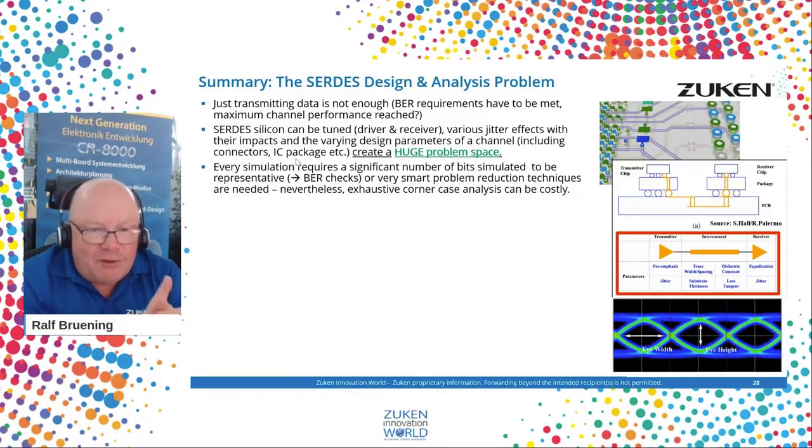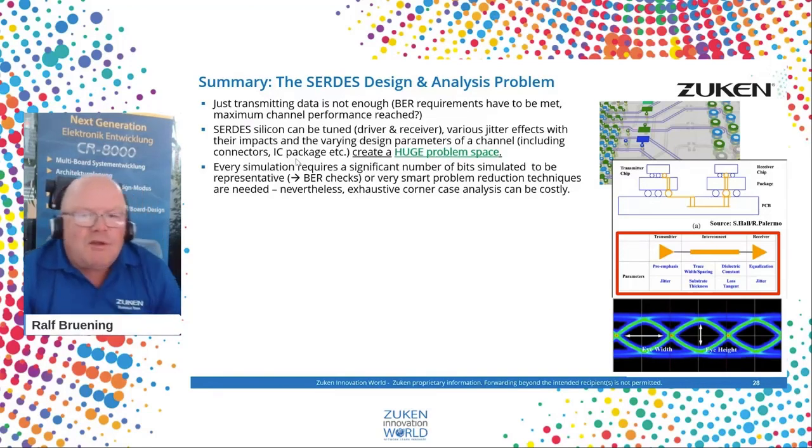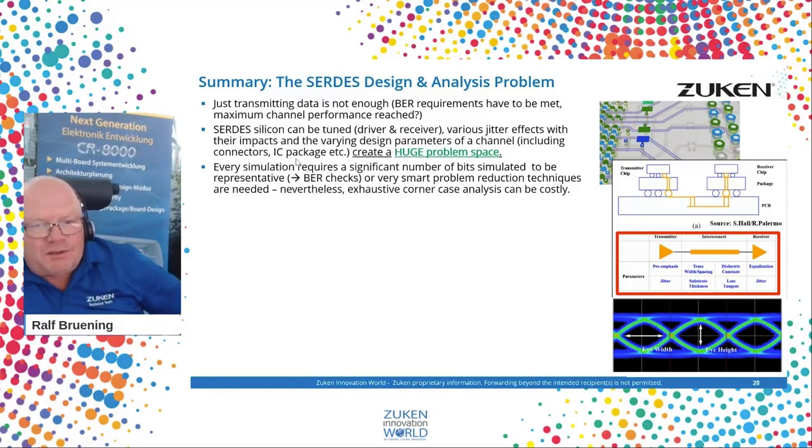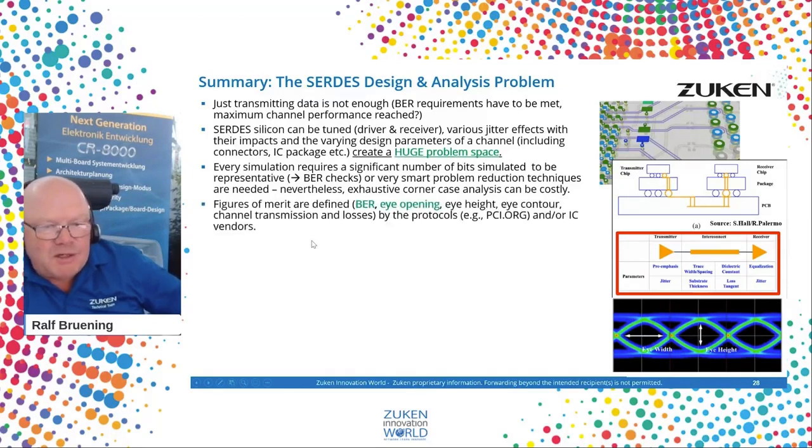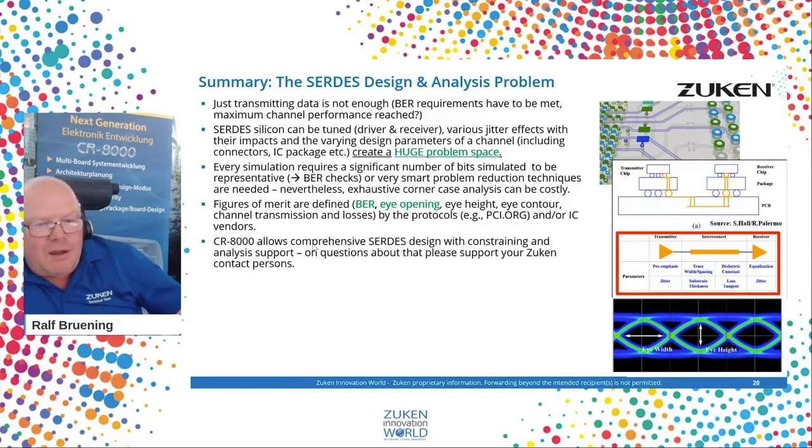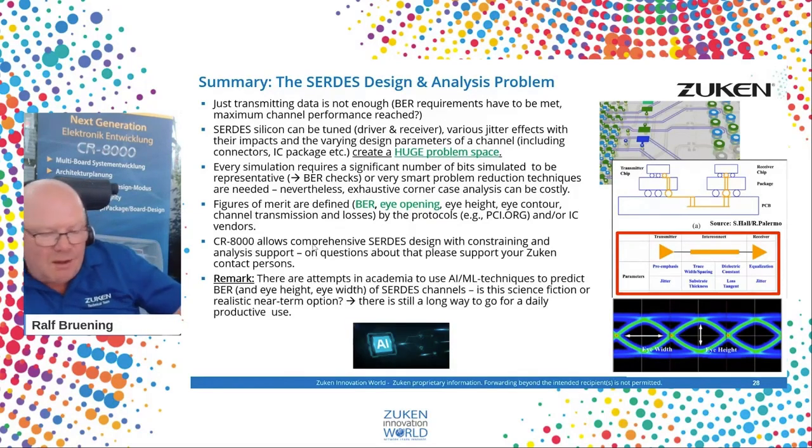As you have to have a significant number of bits to have valid eye diagrams, new simulation techniques have been required. That's what we have implemented by having this IBIS AMI implementation. So that's allowing a fast prediction of the necessary figures of merit, bit error rate, eye opening. And that's all part of our CR-8000 solution.